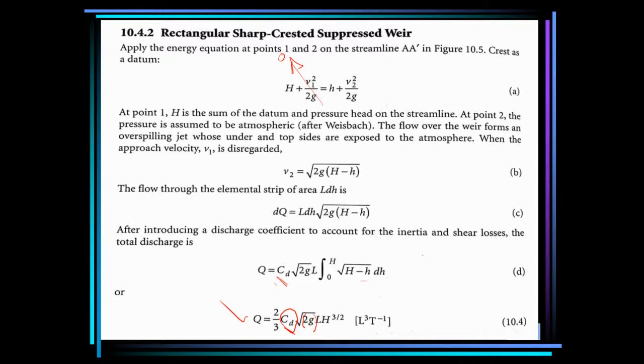If it is going to be installed in a practical channel, a model of it may have to be created in the lab and the coefficient found. Or if it is supplied by a company, they may have done a pilot scale study to find the coefficient of discharge. Whatever the case, the coefficient of discharge has to be known before accurate measurement of flow rate can be done using the weirs.